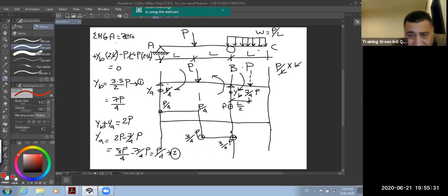The reaction is equal to 7 over 4B. B is not the maximum, because this is up and down. Zero in the section. I need to calculate how much that is. Here is dotted, here zero. Okay, this is your shear force diagram. Where is minus and positive?